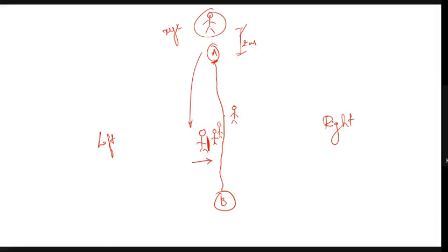Again, this XYZ person will say move towards the left. He will come near this line, and when he comes exactly between stations A and B, in the line of A and B, the XYZ person who is guiding the staff man will say, okay, stop there and place the ranging rod at this point. This is how the intermediate station C is established.